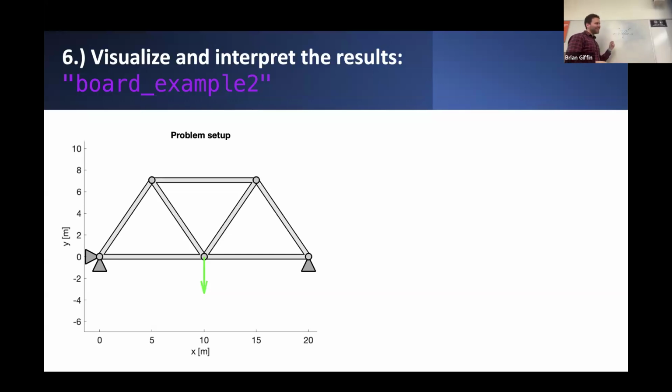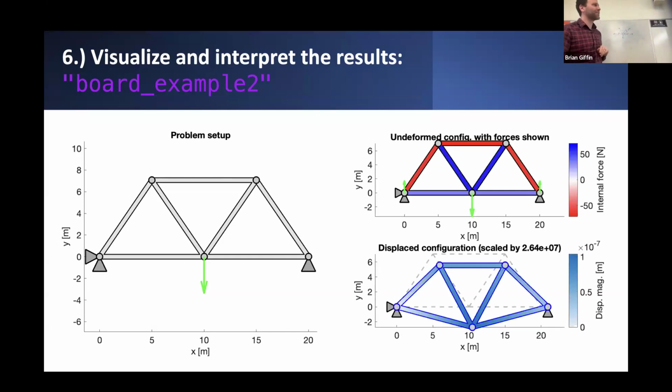Yeah, the same. And the argument here is symmetry, right? The structure is symmetric, the loading is symmetric, which implies that the internal forces distributed throughout the structure should also appear to be symmetric. So we can rationalize that about that plane of symmetry, the internal forces should all look the same. And that's what we end up seeing.